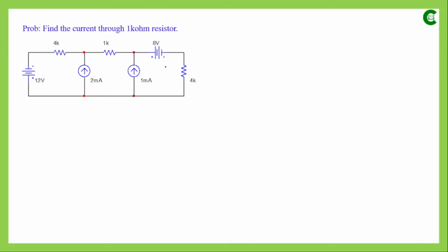So we have the same circuit here, and we will not apply the source transformation method here. As we can see, we have three principal nodes: A, B, and the node at the bottom that we are taking as a reference node. Apart from that, if we exclude that node, then we have two principal nodes, so we will have two node equations here. Let's apply the concept of KCL at node A.